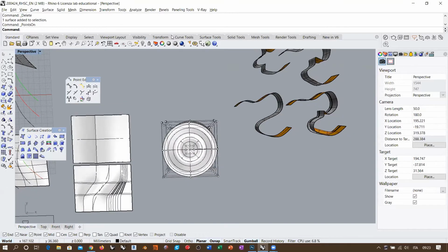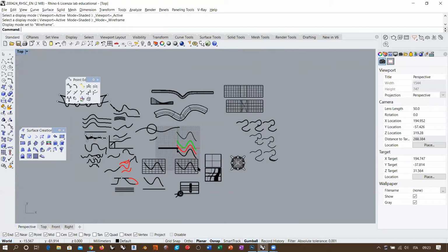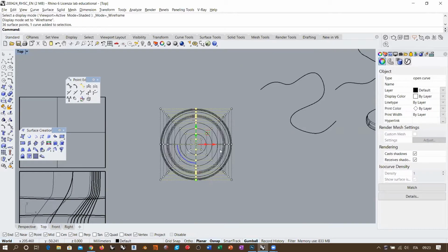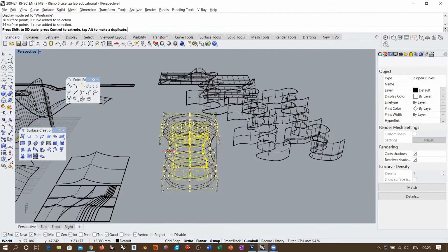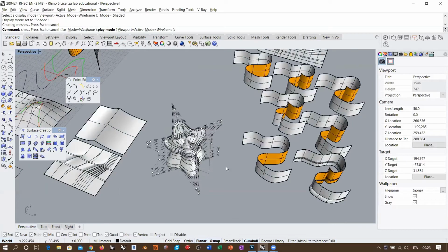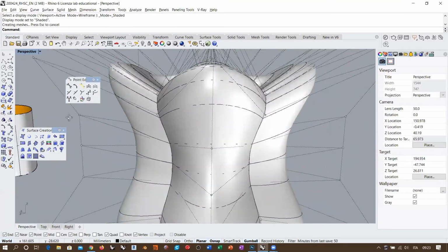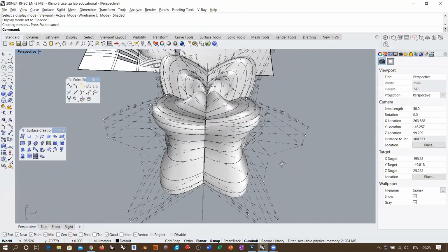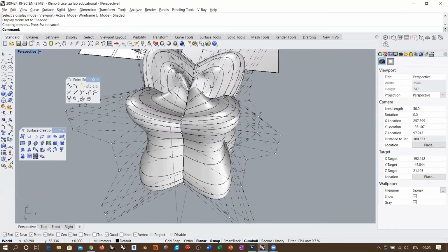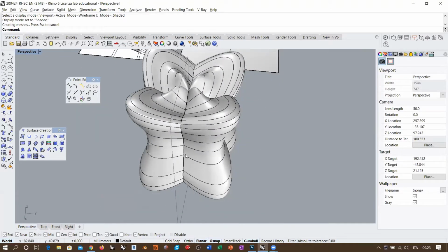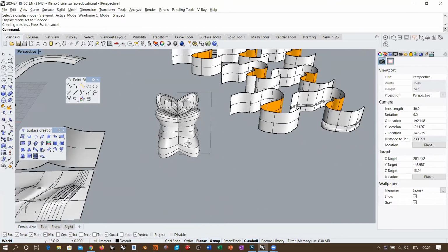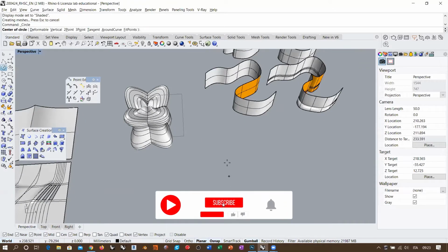So if I take, for example, let me switch to wireframe. If I take this object here and take all these lines of control points and all these lines of control points and do something like this, okay, what I am creating, if I see it with the shaded viewport, you see that I am creating discontinuities along these 4 edges of the surface. Okay, and it's interesting because while here we have a discontinuity that corresponds to an edge, which is the only internal edge, here we don't have internal edges. So you see that, and this is also valid for the standard circle.